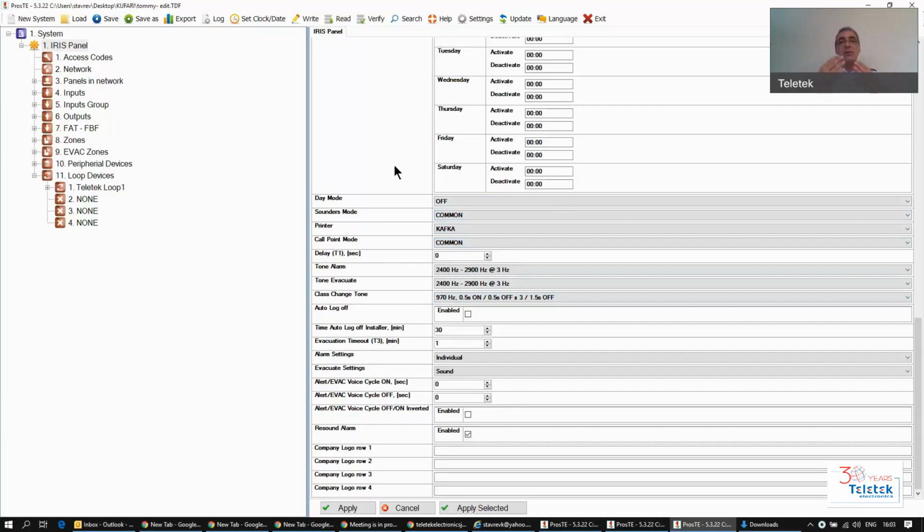And it's very important to understand that this is not delaying of the event. If the event of fire occurs, it's registered into the panel, and the panel will announce it by displaying it on the screen and with the internal buzzer turning on. You are delaying just the action of the sirens.